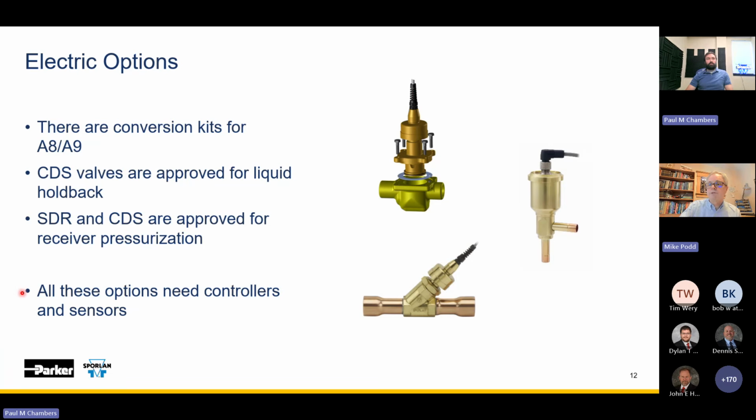We've got a pressure controller and a temperature controller, but more integration in some other devices may be a better approach. Fundamentally, they're going to do the same job, still require that flooding charge. So we're not necessarily addressing that, but we are automating it a little bit. So maybe you can have variable set points as opposed to fixed set points in this case.